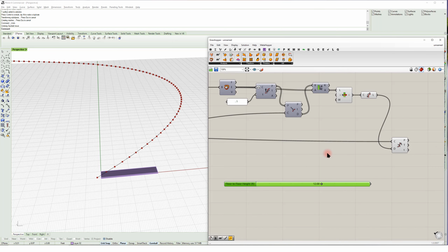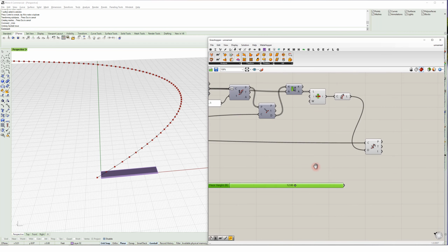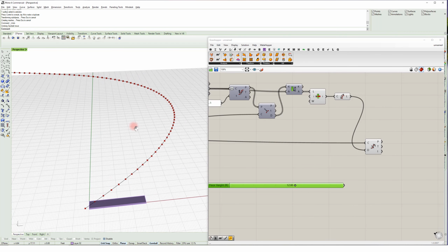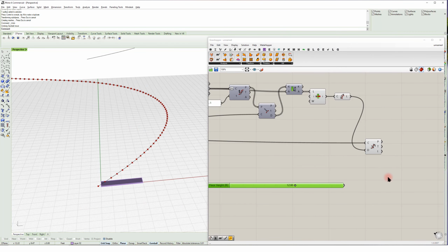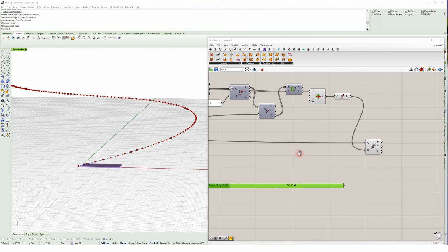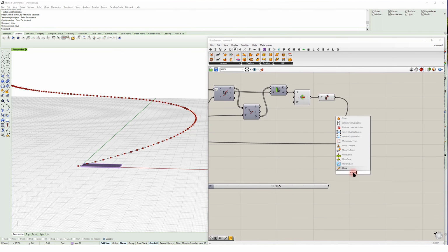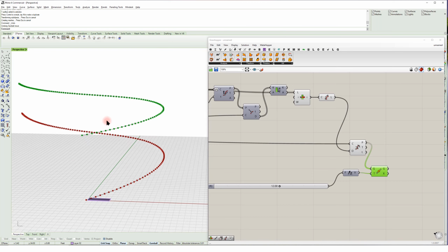And then we're going to start lofting these points up to that height. So if I just did a simple move command by typing move, and then if I double click and type Z to go in the Z direction and just simply moved all these points up, it's going to put them up here.